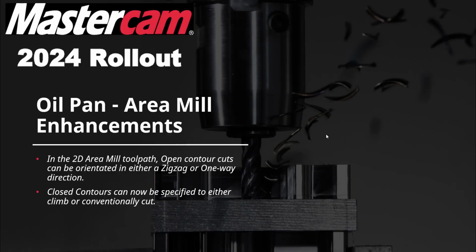We also see some enhancements to area mill in Mastercam 2024. I probably tend to use dynamic roughing versus area mill roughing. Area mill is kind of a parallel spiral, similar to the pocket parallel spiral toolpath, but I do like area mill for finishing floors. If I need to finish a floor, area mill is great for that. It's much better at pocket, especially for outside in type shapes.